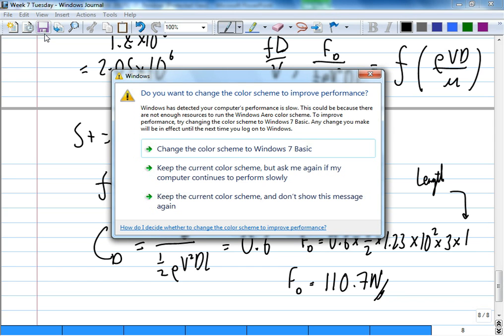Finally, this is another example. Up to now, you might think everything depends on Re. No, that's not the case. Sometimes the controlling parameter is not the Reynolds number. Sometimes the controlling parameter, in this case, is the Froude number, Fr. Because in this case, for boats moving on the surface, the biggest drag component is not from the flow per se, but it's from the waves. It's called wave drag.